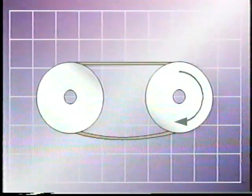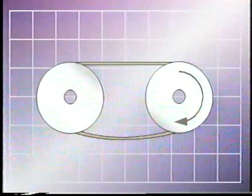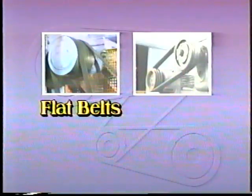Belt sag is a good example of the effect of the arc of contact on drive efficiency. Even when a belt is properly tensioned, there will be some sag. If a belt sags away from the pulleys, the arc of contact is decreased and power is lost. To prevent this, an idler pulley may be used. This prevents sag and increases the arc of contact. When a belt sags toward the pulleys, the arc of contact is increased and an idler pulley may not be required. Let's take a closer look at how these belt-driven friction drives operate, beginning with flat belts.